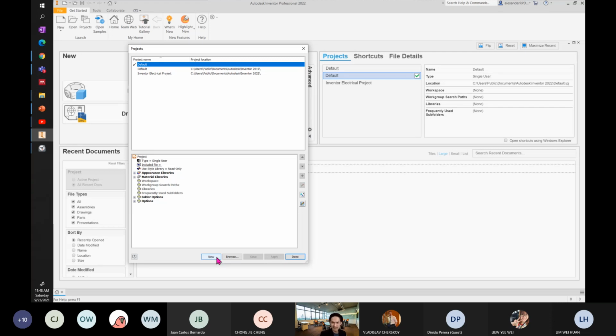If you just install Inventor, maybe just 6-7 GB. But if you install the library, it may double the size. If you install the full package, I did try that, it can go up to 25 GB, just the software and the library together. So make sure that your laptop, your machine, is able to support that in terms of space.